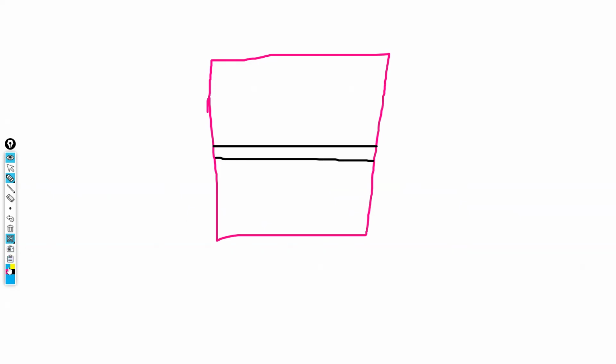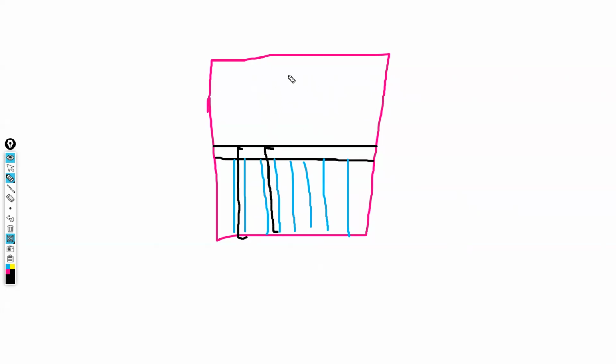Now, if these are the ribs, these are your max spans. Okay. Now, the reinforcements are going to come between the ribs, like from this point, and they'll end there. You get it? They'll end in this beam. Also, this is going to end in this beam. Then for the solid slab, it's going to be separate. That's why this beam is very, very key. We added it there.